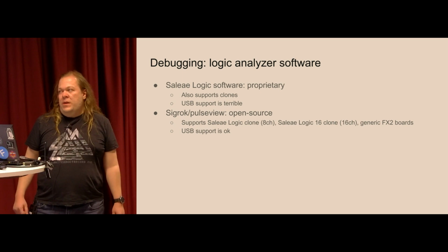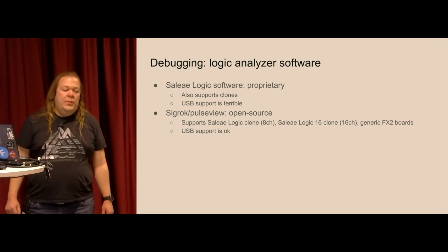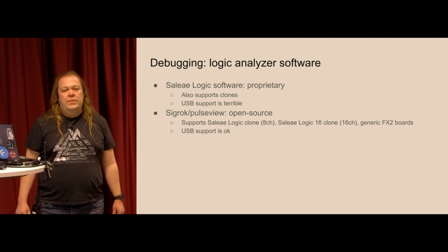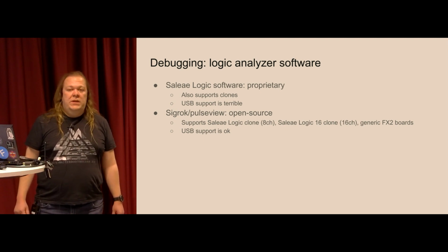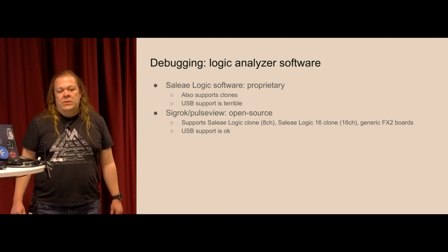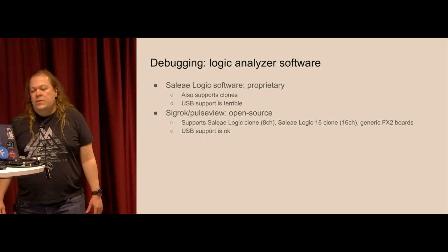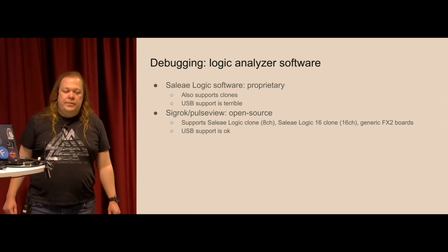But it is capable of exporting to VCD format or some other binary formats, and these formats can be imported to the second software option we have. And this software option is open source. It's called Sigrok. This Sigrok is like a base library which supports multiple logic analyzers, and PulseView is a graphical user interface for it. So you can use it directly with the probes which are supported by this software, for example, all the clones and some generic FX2 boards.